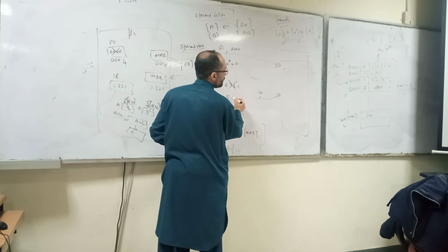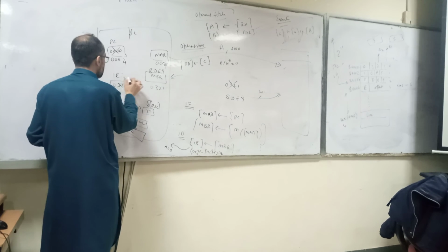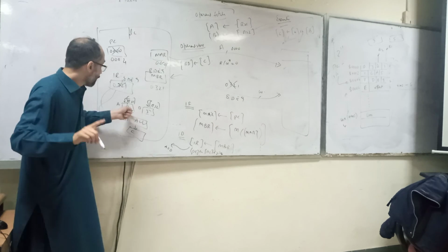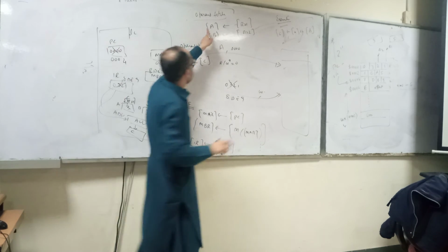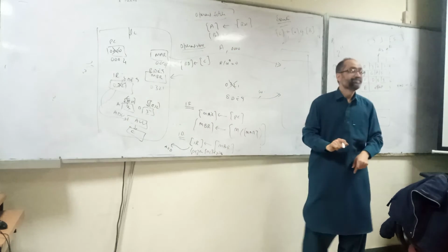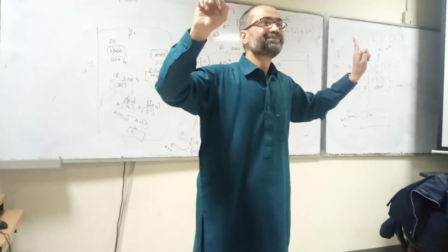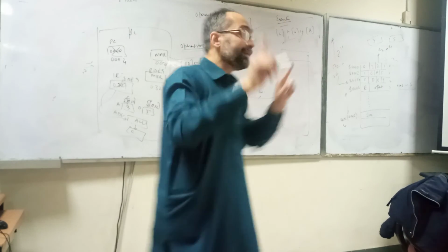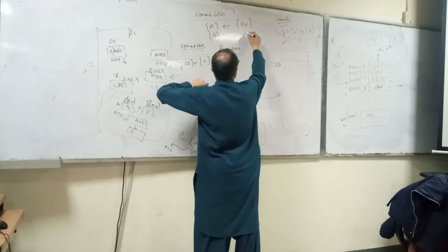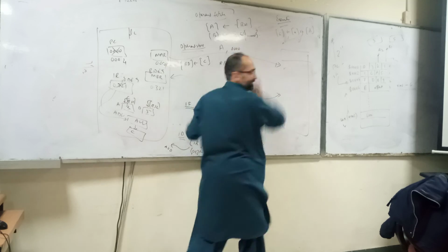What is the data now? 8DE9. Add means add, but add I is not register. So what will be loaded in the operand fetch? A will be RS1, and B will be the immediate value. But the immediate value is now 4 bits and the register is 16 bits, and now you are adding. So B will be the immediate value with sign extension. Why sign extension?